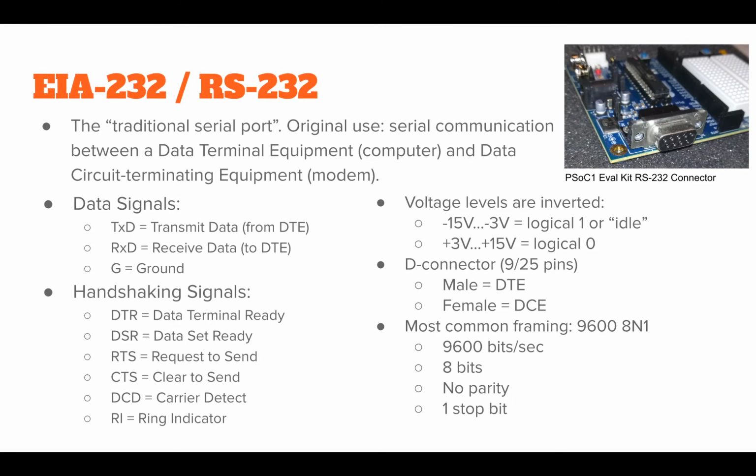When we are talking about UART, it's also good to talk about this RS-232, which is the old-fashioned, old-school serial line, or actually currently it's Electronics Industry Association norm 232, and that's currently what defines the logic levels and that kind of thing. So data signals, transmit and receive data, and ground are required. That's the simplest form of a 232 bus.